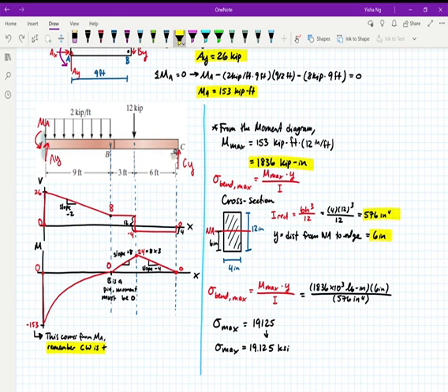All right, we made our shear moment diagram. Very, very last steps. We can see from the moment diagram that the biggest absolute value number is 153. And so I can say my M max is 153. This is an instance where I'm taking the absolute value because I care about the maximum stress acting on the beam as a whole, not whether it's in tension or compression. So my M max is 153. This is in kip feet.